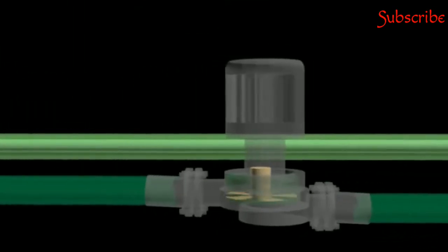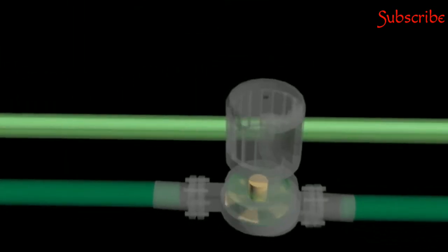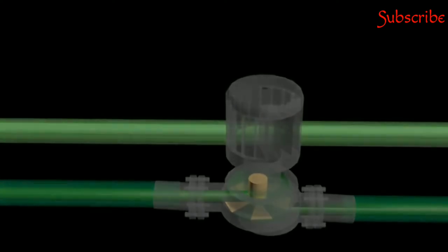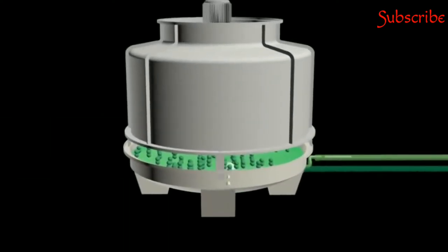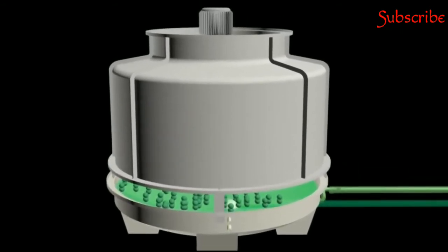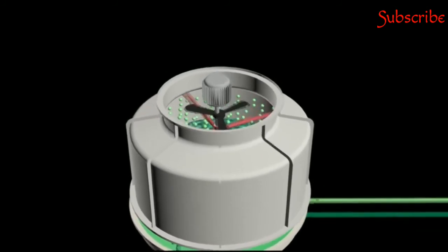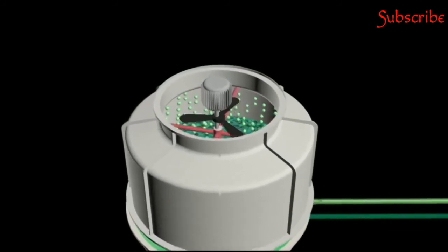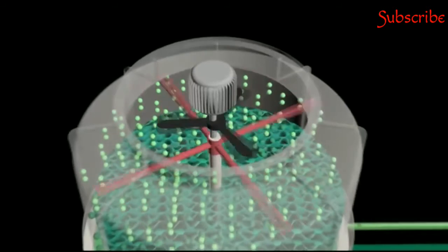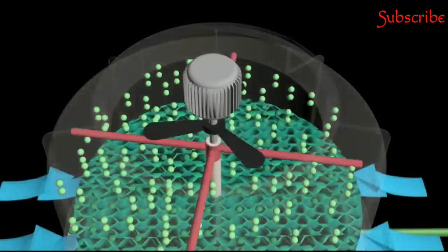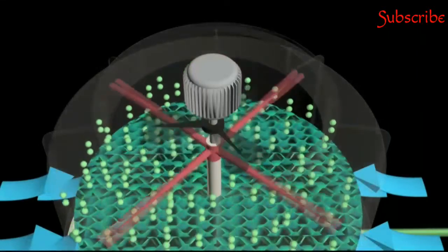From the condenser in the chiller, condenser water flows to the cooling tower with the help of a centrifugal pump. This water is called condenser water return. This condenser water will pass through the rotating sprinkler blades on the cooling tower. The rotating blades use pressure generated by the condenser water itself. Water will gush down through the fins to reduce the speed of water going down.